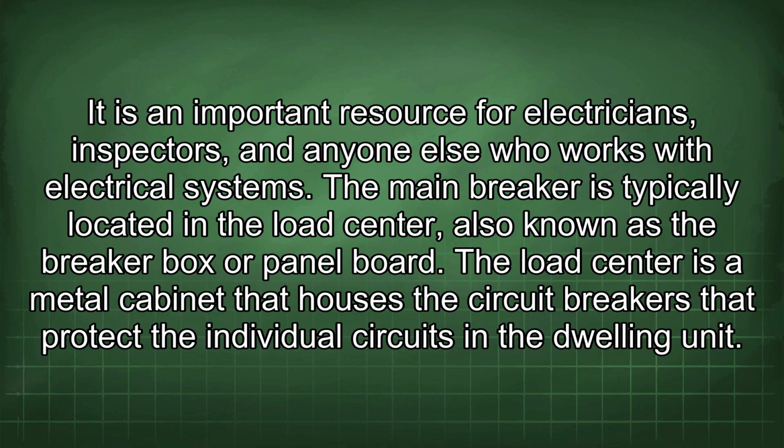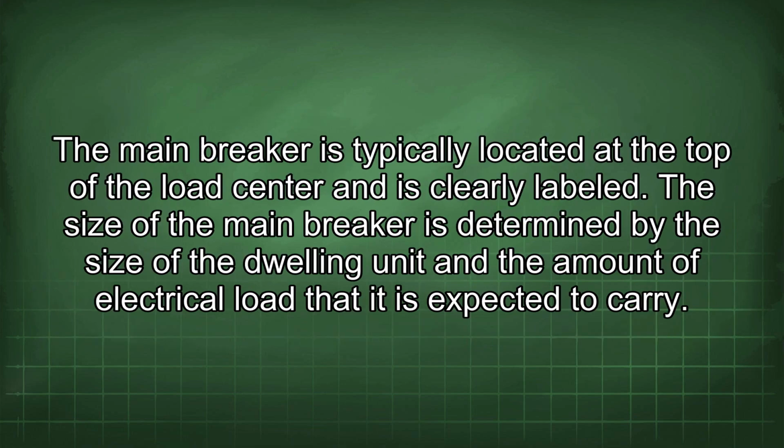The main breaker is typically located in the load center, also known as the breaker box or panel board. The load center is a metal cabinet that houses the circuit breakers that protect the individual circuits in the dwelling unit. The main breaker is typically located at the top of the load center and is clearly labeled. The size of the main breaker is determined by the size of the dwelling unit and the amount of electrical load that it is expected to carry.